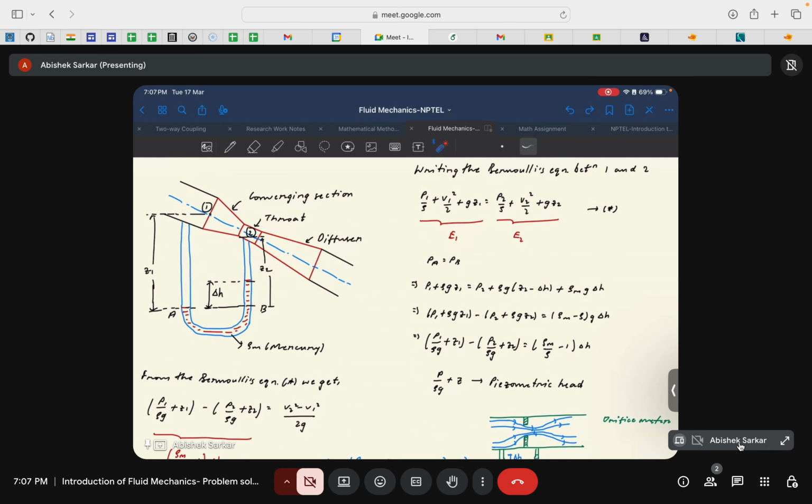To prevent losses because of flow separation, the diffuser is usually longer than the converging section, so that the flow can gradually expand, properly follow the small diverging angle, and then resume back to its initial flow velocity.